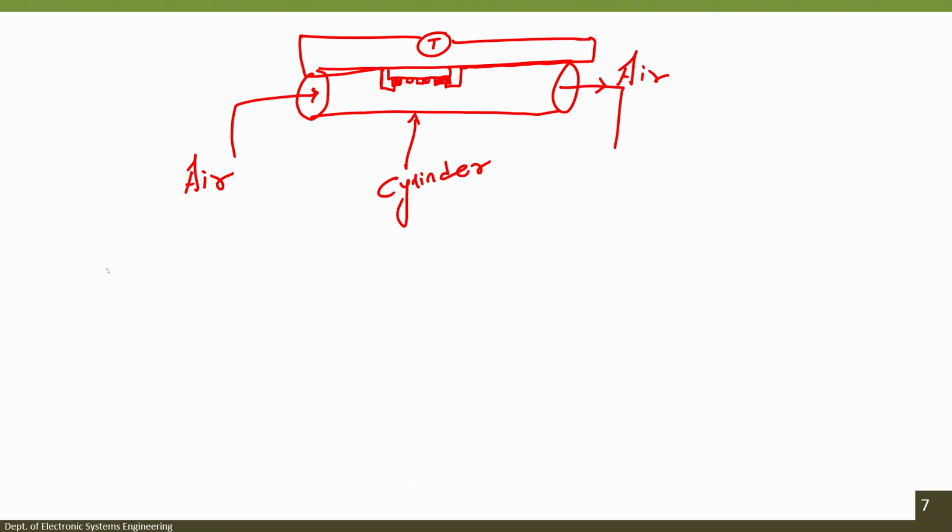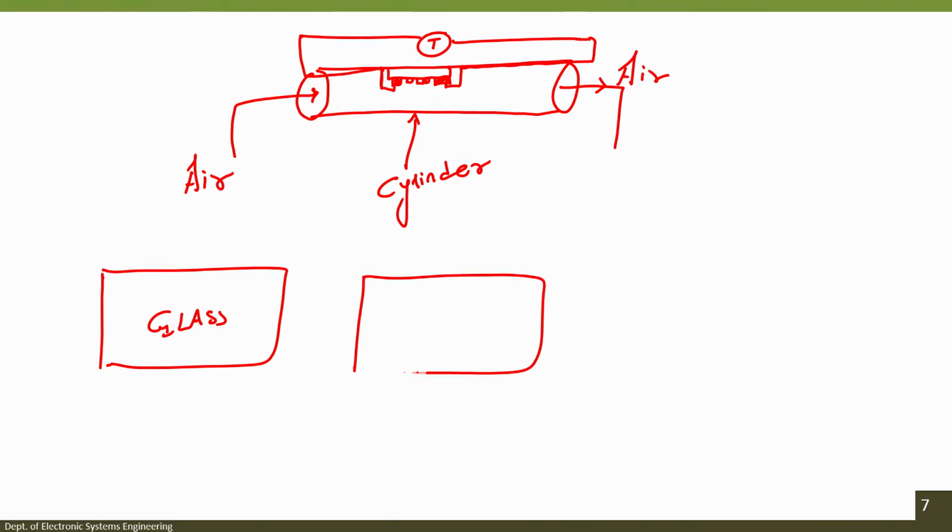What we will do, let us say if you do not have a silicon wafer in your college or university, you can take glass. Now, what is the difference between a silicon wafer as a substrate and glass? In a silicon wafer, I cannot directly deposit metal, I have to grow silicon dioxide. I generally grow silicon dioxide.